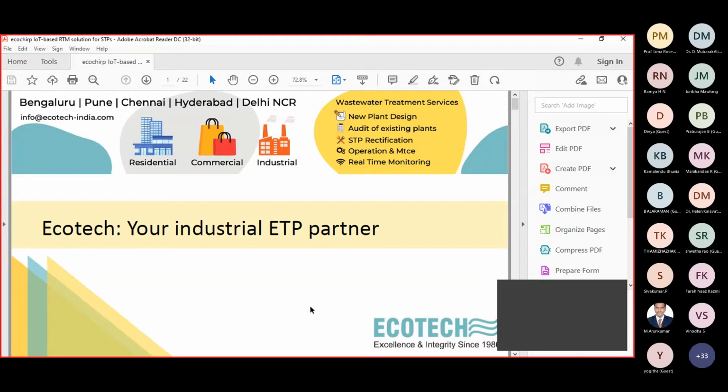Just as in the case of the tertiary units, sand filter and carbon filter, you cannot use them as the main treatment units. These are also considered final polishing units. The bulk of the treatment should happen prior to these tertiary treatment units, either in the primary treatment or secondary treatment. So that is the concept any environmental engineer must have.